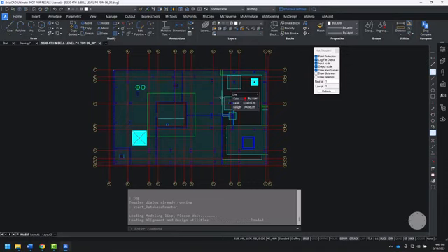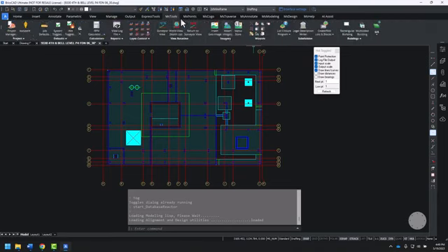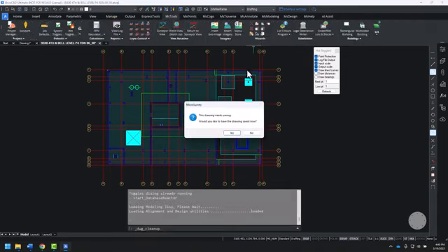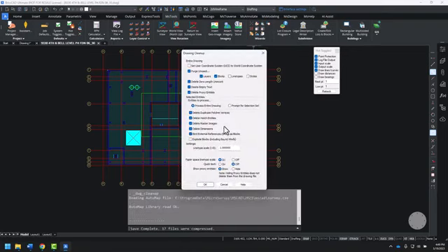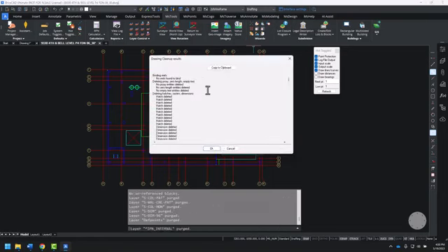When we first open a drawing that's been sent to us by our clients for layout, on the MS Tools ribbon, I want to launch the Drawing Cleanup Wizard. From the Drawing Cleanup Wizard, we can do things like delete hatch entities, remove images, bind external references, and purge unused layers and blocks. We get a summary of everything that was removed.